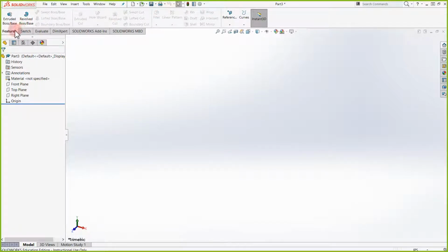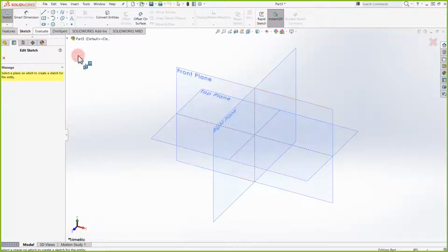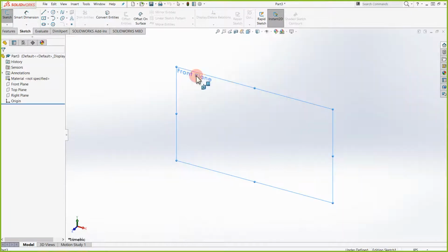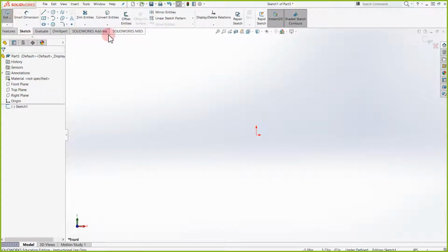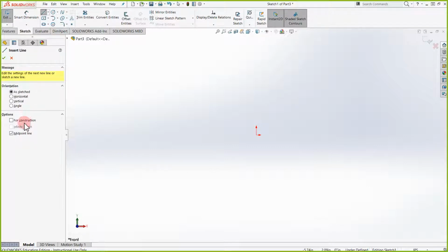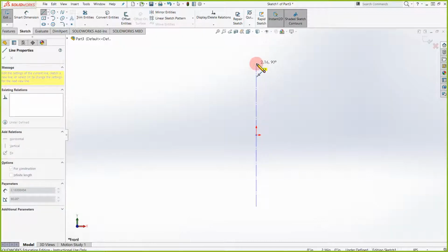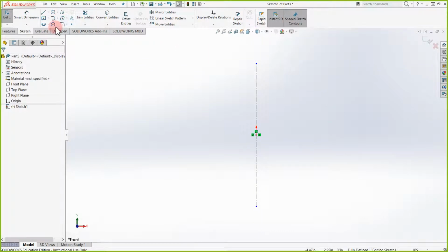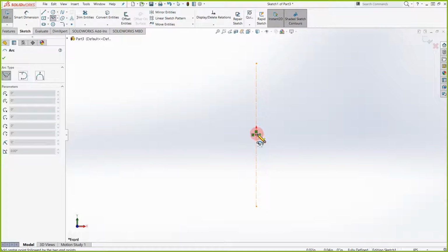We're going to go to do our sketch. On the front, I'll do this time. So what does revolve do? It takes the shape you're building. So I'm going to make a center line. I'll use midpoint, and I'll make a construction line for this. And I'll go up, and I'll just put it any dimension right now. Then I'm going to do an arc. So let's do a center point arc from here to here to here.